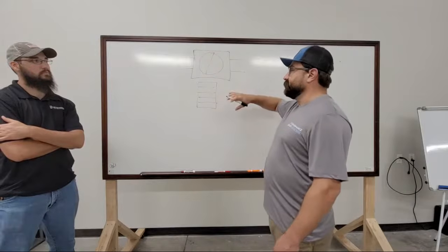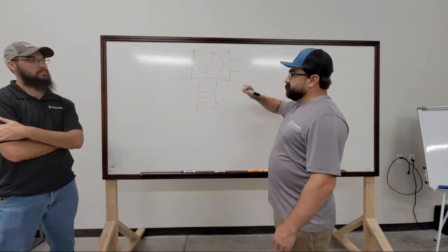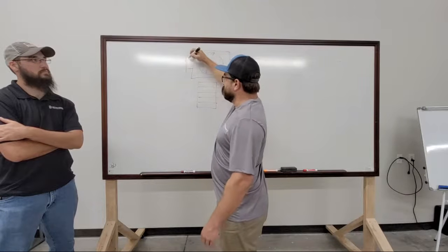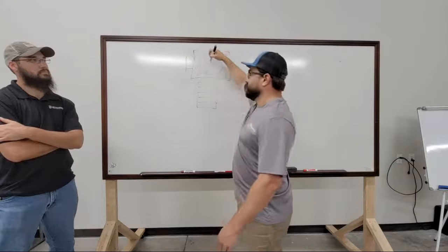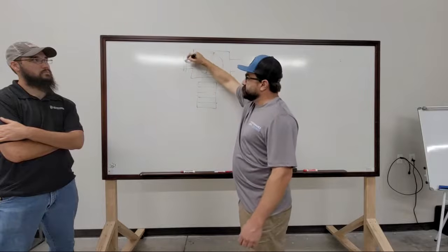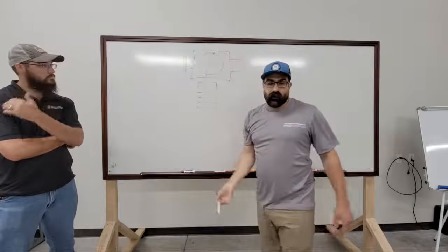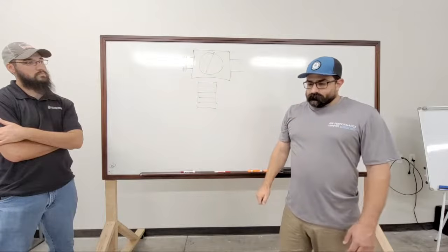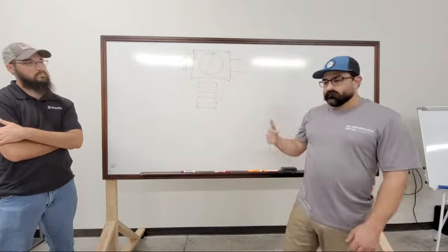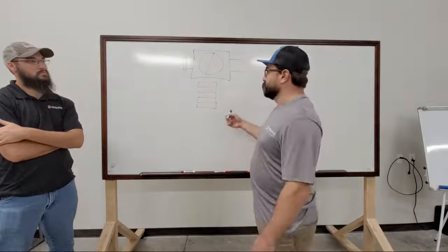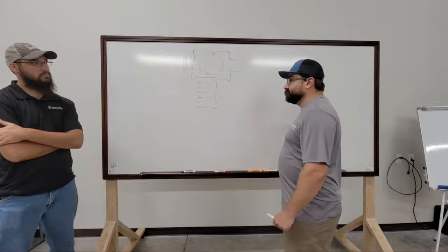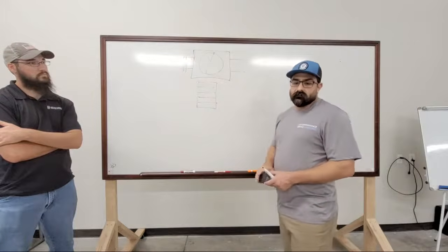All of these boxes, if it is a true VAV, will have a crossflow sensor in the ductwork upstream of the damper that measures velocity pressure. And through math, which we'll touch on later, converts it to flow through either a, dang it, what's the pneumatic term? I'm drawing a blank. A velocity controller, or through an actual DDC controller, converts it to CFM readings, and so forth. VAVs are real simple. They can have reheat, they cannot have reheat. Other than that, it's just a damper.